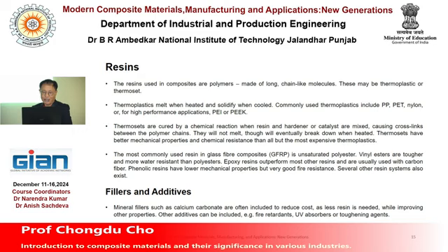If glass fiber is the reinforcement, then we say it's a glass fiber reinforced polymer, GFRP. If carbon is the reinforcement, then carbon fiber reinforced polymer, CFRP. And etc. We need to use fillers or additives, not just a matrix and a fiber. For processing purposes or some kind of stability of performance, we need to add fillers or additives in addition.